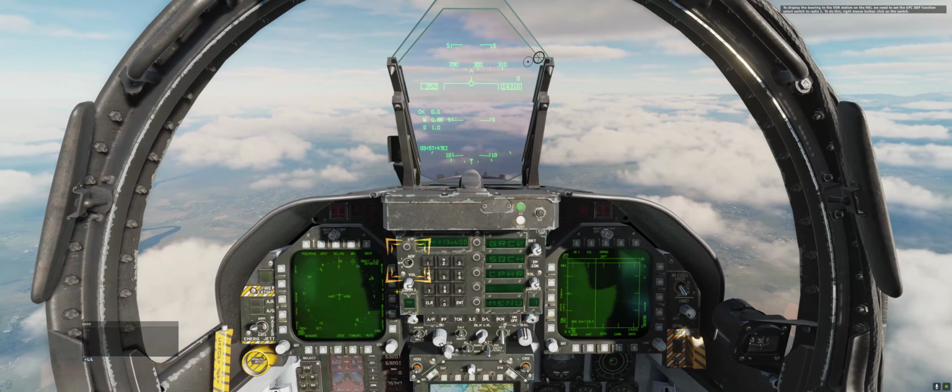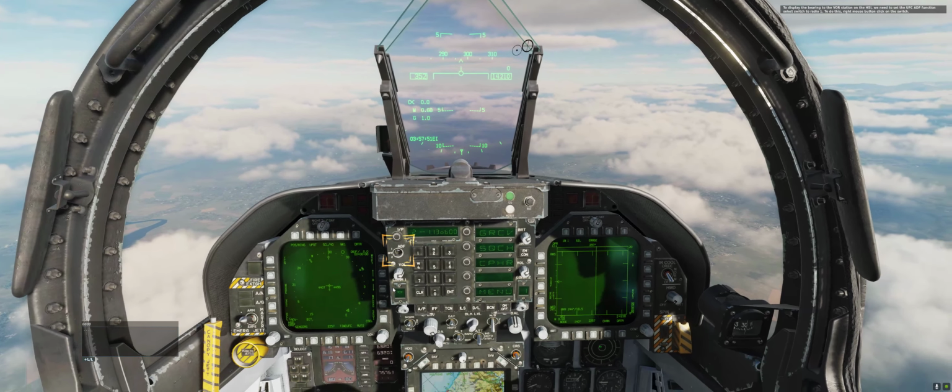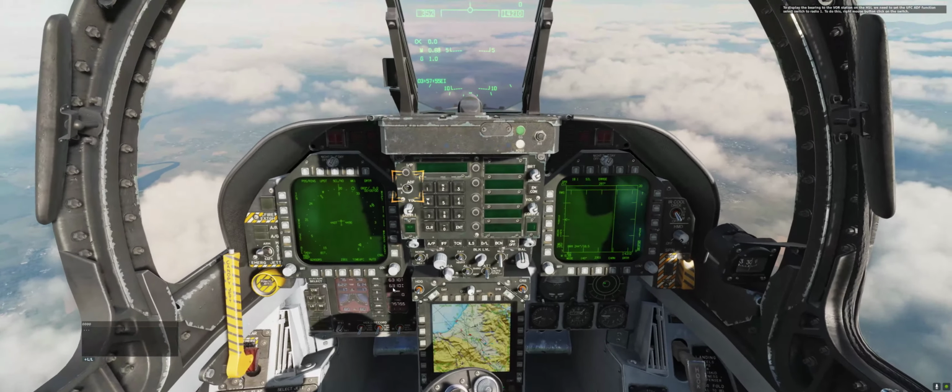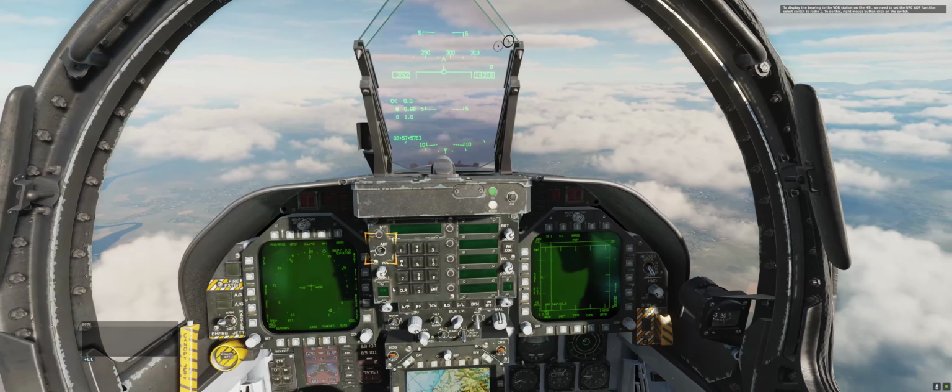Press spacebar to display the bearing to the VOR station on the HSI. We need to set the UFC ADF function select switch to radio 1. To do this, right mouse button click on the switch. With that done, you will now note a small circle along the outside of the compass rose at the 1 o'clock position. This is your bearing to the ADF signal. There is no range information though. As you can see, ADF is quite simple. Let's move on to TACAN.